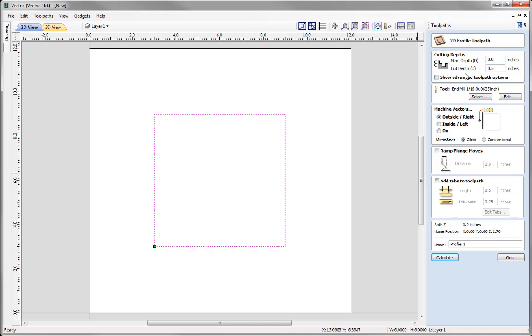And so the next option in the list is the cut depth, and this is where we specify how far down we want to cut into the material. Now in this case I want to cut the square out of my material block, so I need to cut the entire thickness of my material, which we know is 1/2 inch as we just set up the material earlier. So what we could do in here is we could enter that value of 1/2 inch. Another tip here is if you didn't remember the value that you set your material thickness to, you could simply enter Z and equals, and the software will input the value that you entered for that material thickness in the form for you there using the calculation Z equals.